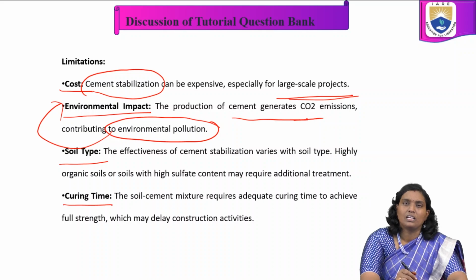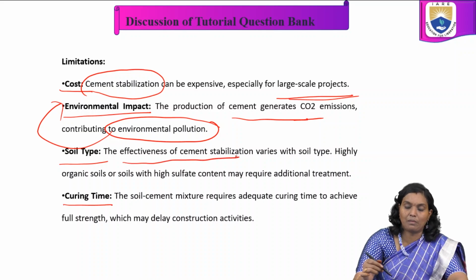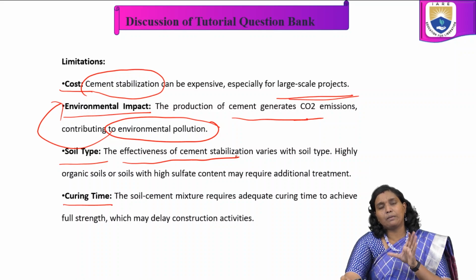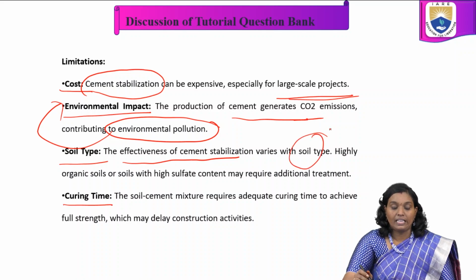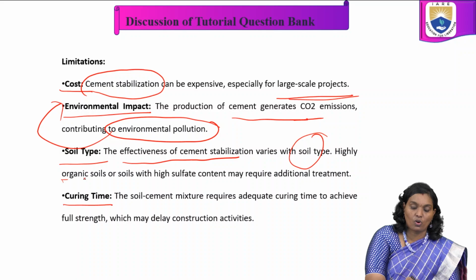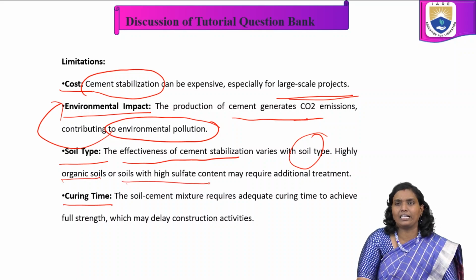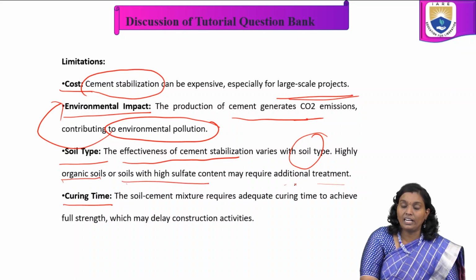And one more: it depends upon the soil type. The effectiveness of cement stabilization varies depending on the soil type. Highly organic soils or soils with high sulfate content may require additional treatment.